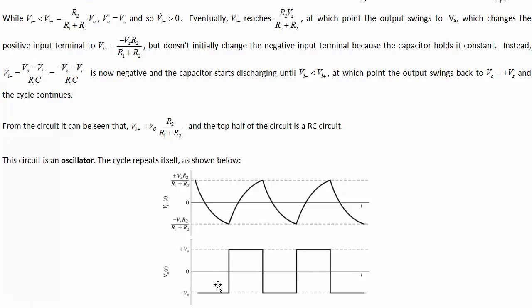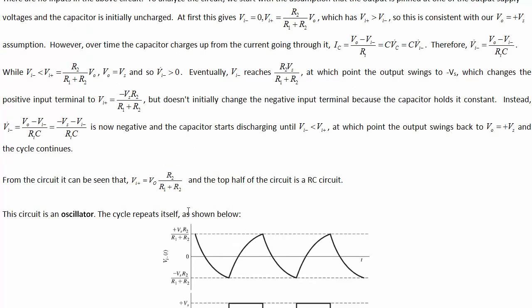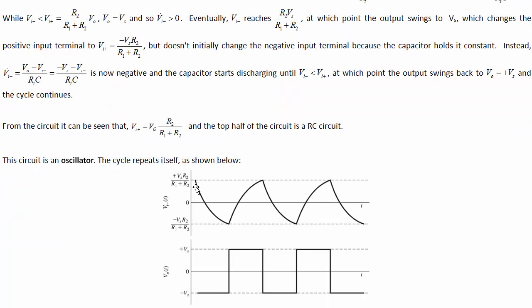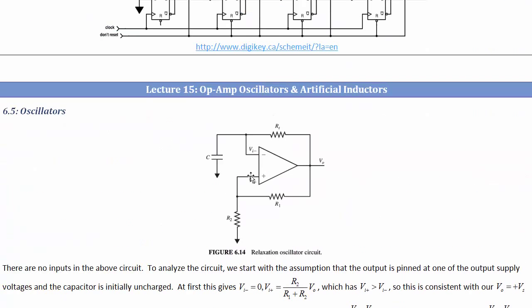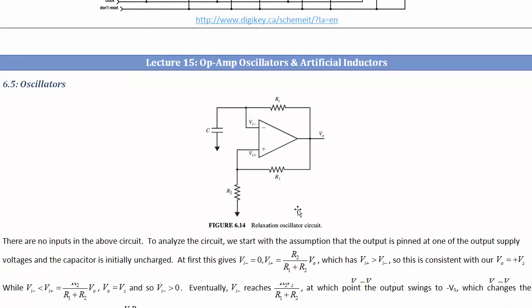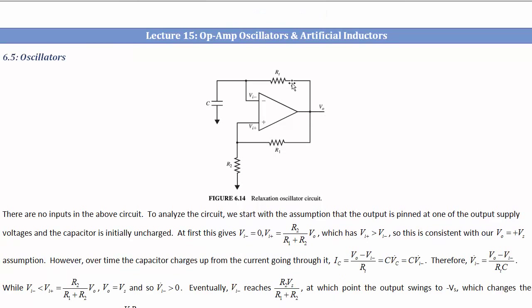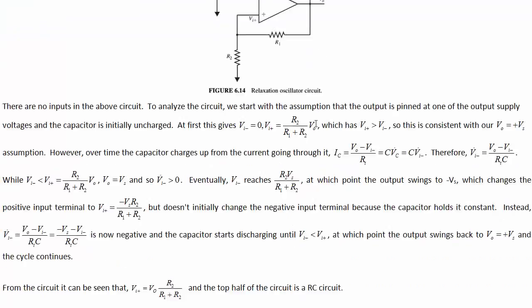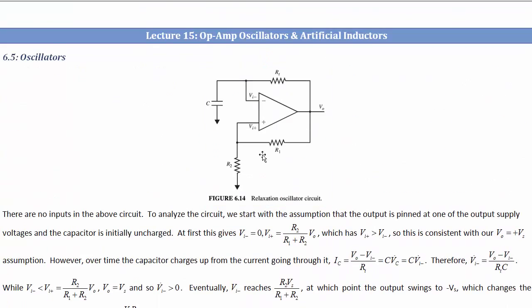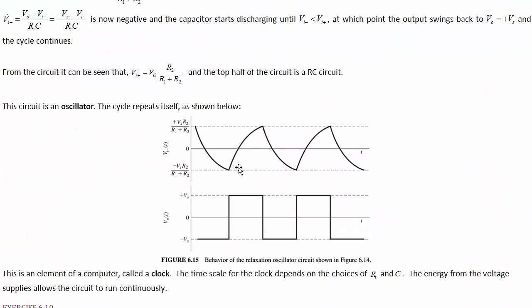It's like if the switching point became 0, but then 0 also became the point that we're artificially approaching, or rather infinitely approaching, for the discharge of this RC circuit. So we're never actually going to reach that point. Now in practice, if we can get arbitrarily close to it, then any small oscillation in the voltage will cause the comparator to switch again. But it's not really as reliable of an oscillator in that case.